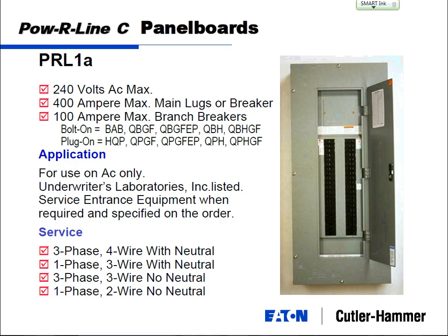May I say something about this one? Yep. Because this is related to the project that we're going to use. So this panel will be used for the lighting panel and the receptacle. We have a 100 amp receptacle panel and a 225 amp lighting panel. They will go 208 three-phase. So that would be right. Am I right here with the choice? Yep. So when you guys have cut sheets, that's what you're looking at for your cut sheets.